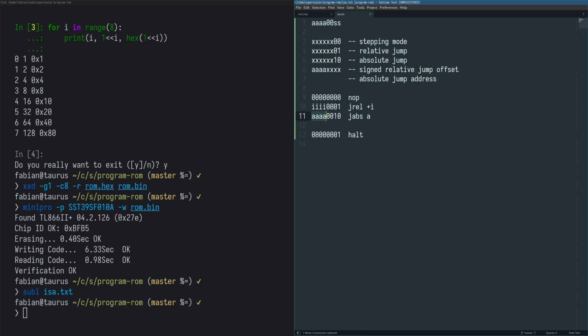Well, the program counter is going to jump back to address 0 and continue execution there, which is actually roughly equivalent to doing a reset of the CPU and just starting at the top from the program. So again, we can copy this instruction and fill in the topmost 4 bits as zeros and then call it a reset instruction.